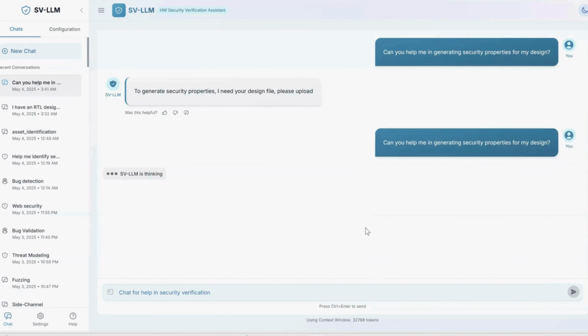To demonstrate the example, the design file implements a parameterizable buffer with write pointer, read pointer, and a counter that tracks occupancy. On each clock, a valid write request enqueues data when full is low, while a valid read request dequeues data when empty is low. A synchronous reset initializes all pointers and the counter to 0.